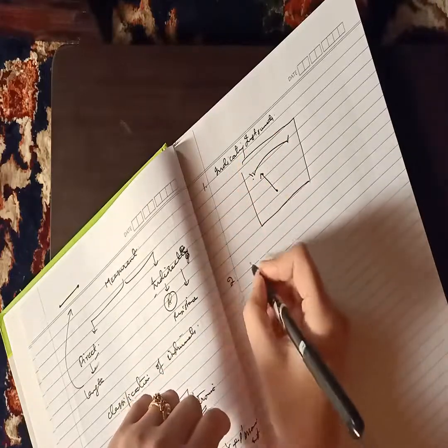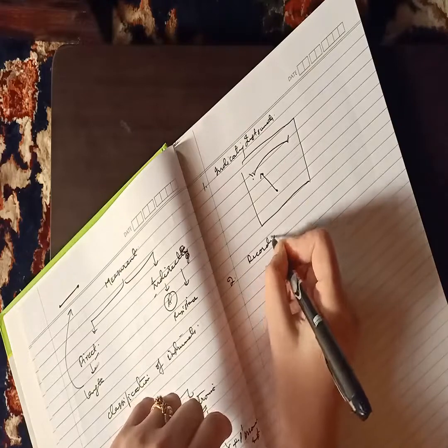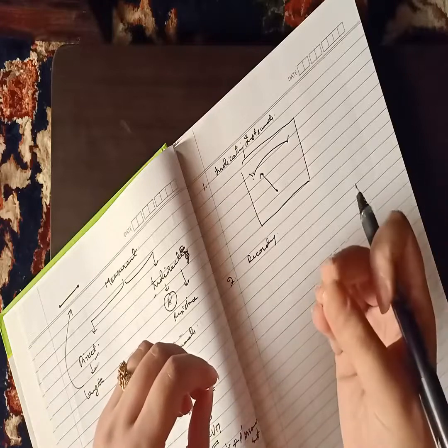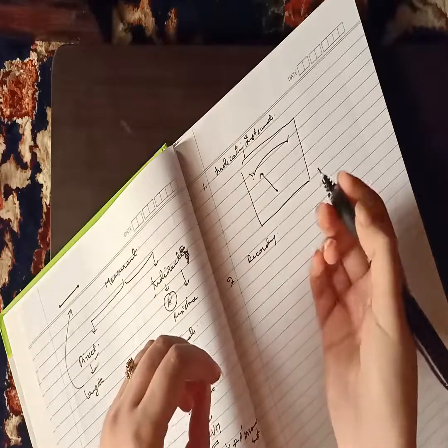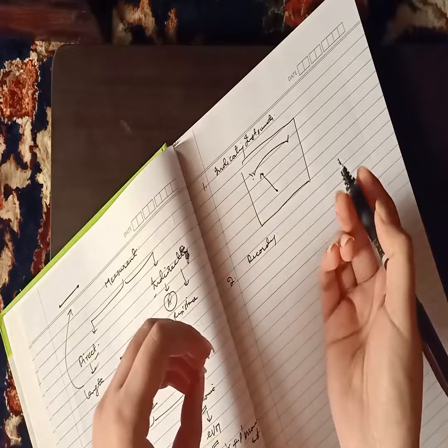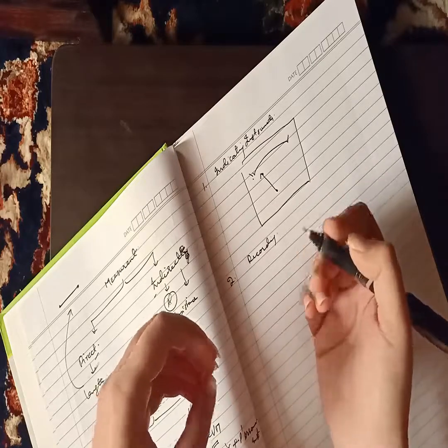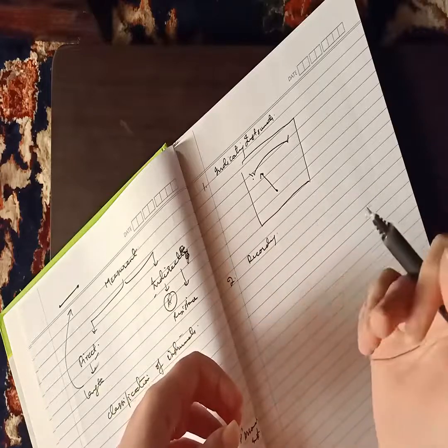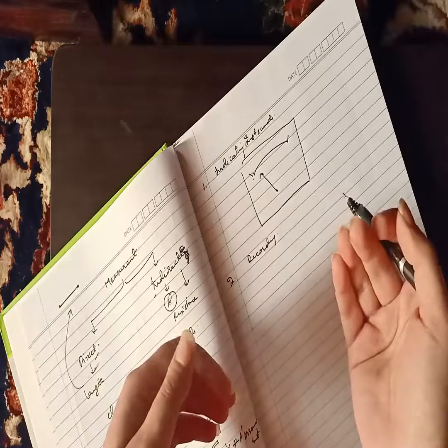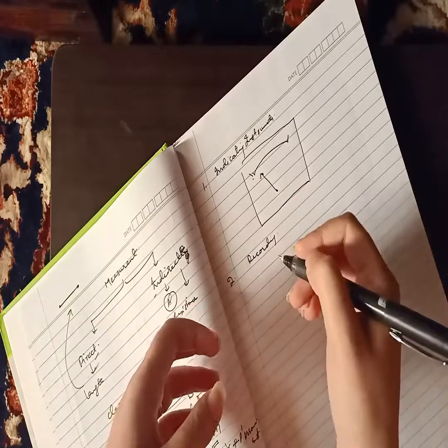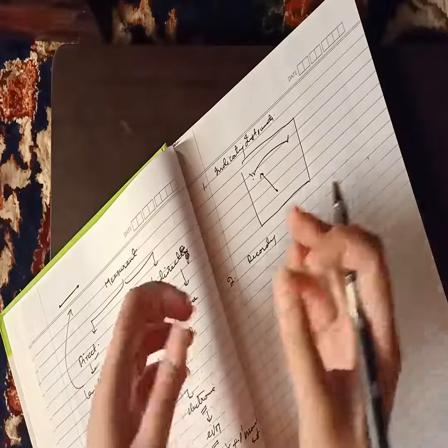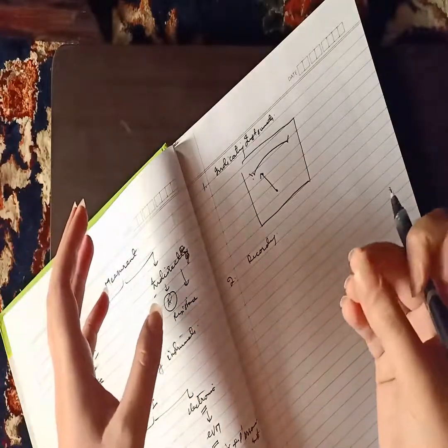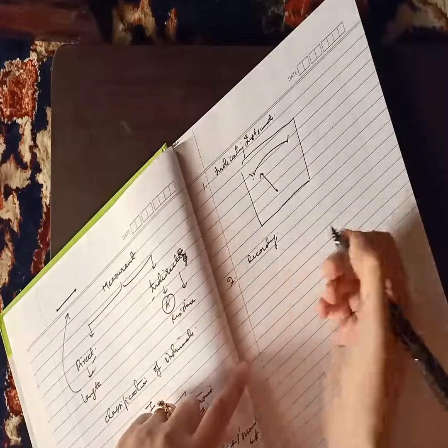Now then there is the second category, which is the recording type of instrument. What is a recording type? It tells you continuously. Say if I'm measuring a current, the current in a particular circuit mostly remains constant for a particular duration of time, but say if I have to measure a heartbeat or something like that which varies continuously over time, then to measure that quantity we also have to record it along with it, because at one point it can be one way and at another point it changes in a very small instant of time, and I need to record it along.